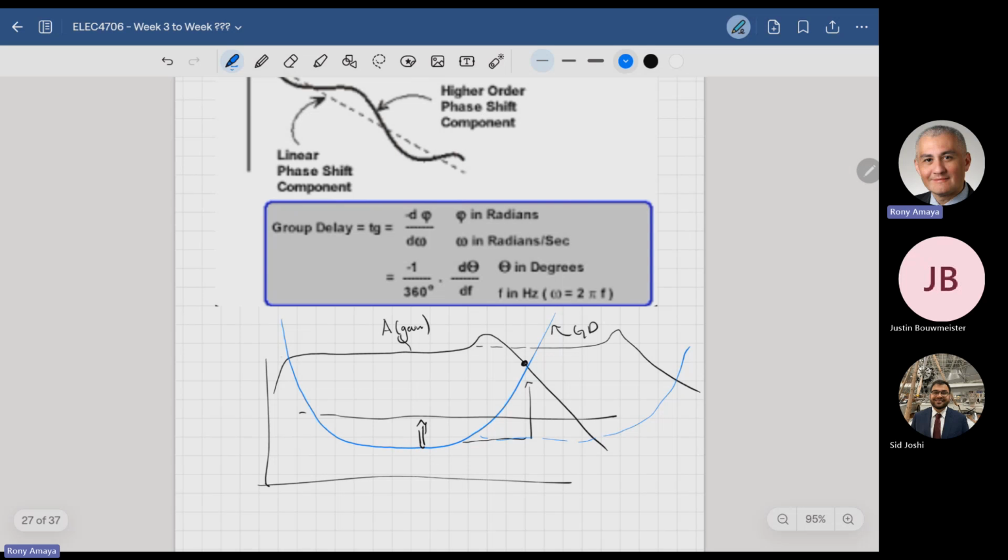I explained 15 minutes ago that you couldn't, because there's another secondary effect that we have to deal with. Why can I not just extend it so that within the bandwidth of interest, which is this dot here, I have now flattened the group delay and flattened the gain? If I extend the bandwidth, I can flatten the group delay and the gain. The peaking happens later, and this tuning of the group delay happens later. But what is the problem?